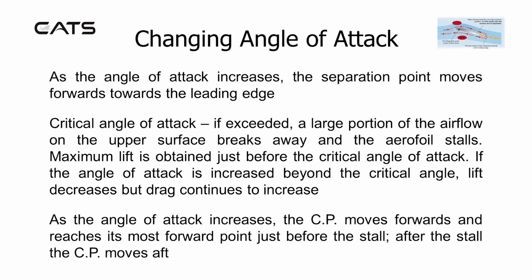As the angle of attack increases, the centre of pressure moves forwards and reaches its most forward point just before the stall. After the stall, the centre of pressure moves aft.